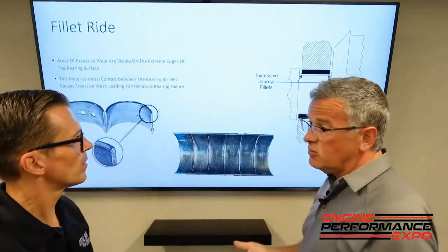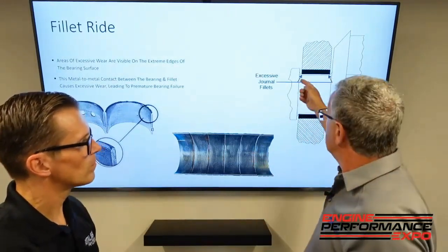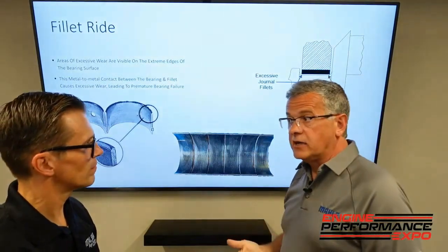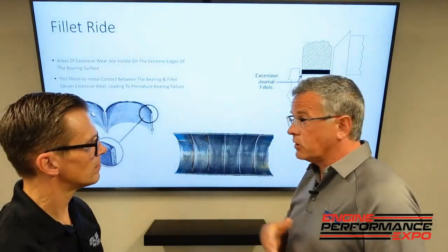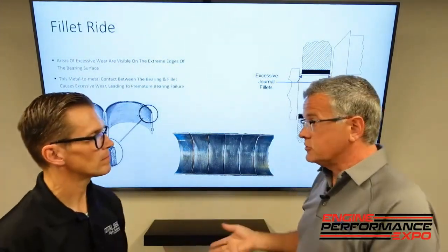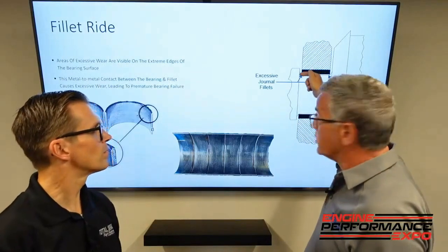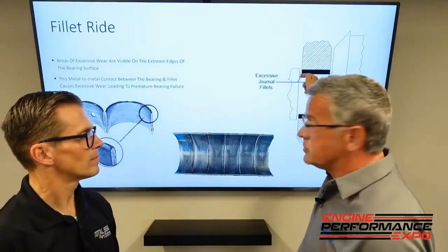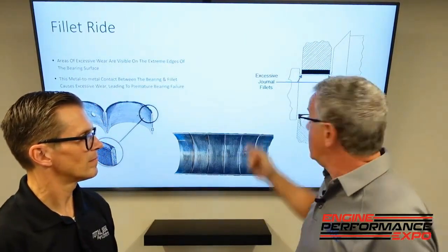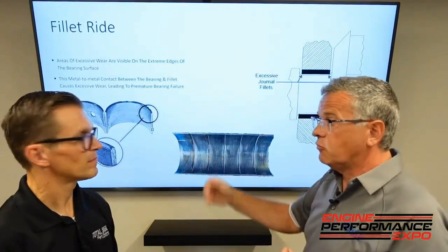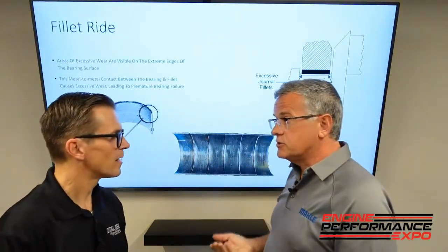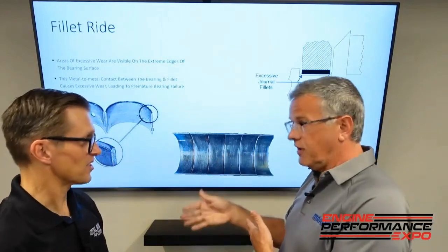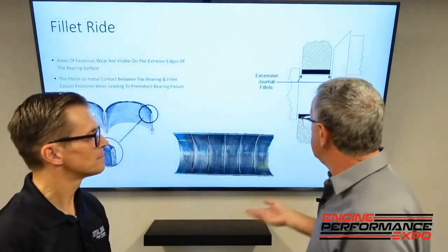Now, in some cases, it'll wear in. But if it's bad enough, when I worked in the NASCAR shops, I was in charge of NDT, and you actually can get to a point where you put a stress point into the fillet. A stress point at a fillet is the first place it will want to crack. That's no good. So you're inducing a failure mode into the crank.